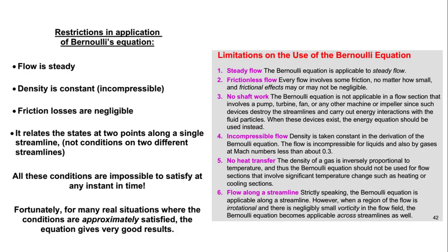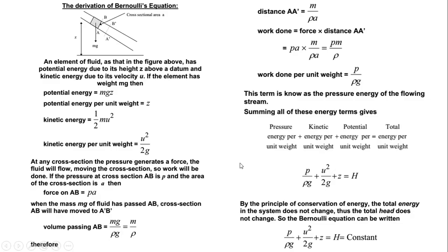So if there is heat transfer, and there is shaft work, and there is friction, or the flow is unsteady, we will not be able to apply the Bernoulli equation. We can only apply the Bernoulli equation when these conditions are met.